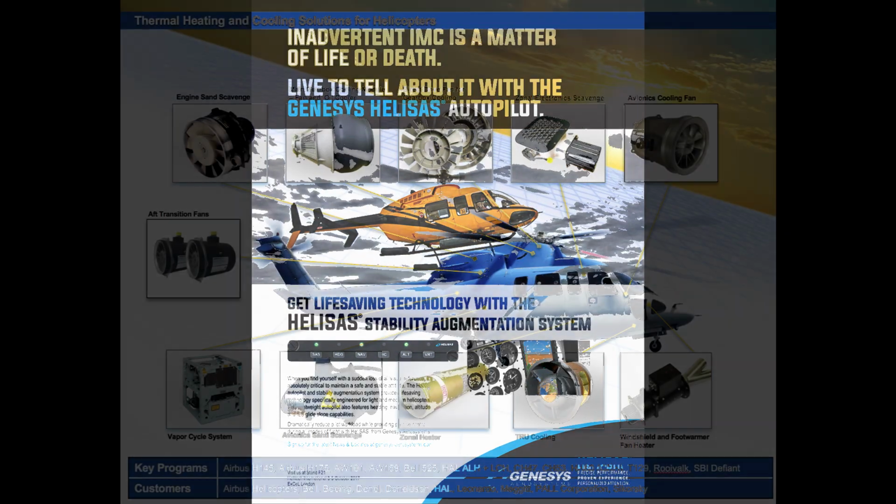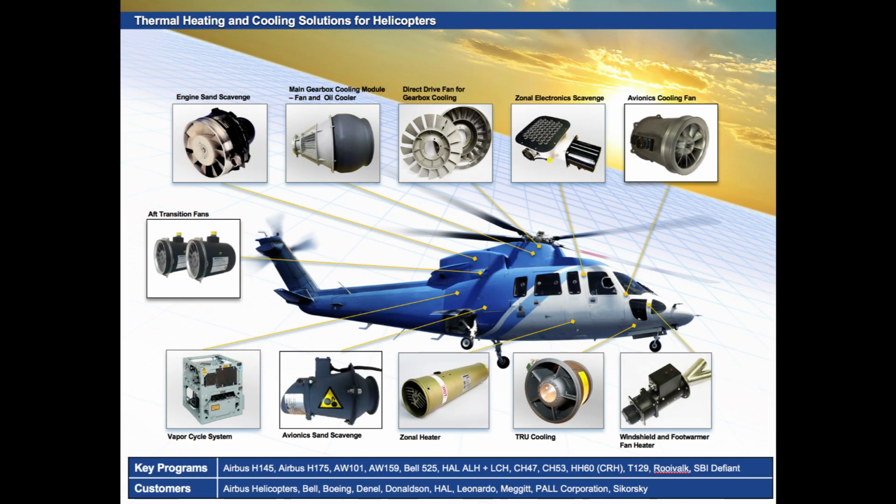Environmental systems. Heating and cooling the helicopter cabin can be accomplished in different ways. The simplest form of cooling is by ram air. Air ducts in the front or sides of the helicopter are opened or closed by the pilot to let ram air into the cabin. This system is limited as it requires forward airspeed to provide airflow and also depends on the temperature of the outside air. Air conditioning provides better cooling, but it is more complex and weighs more than a ram air system.